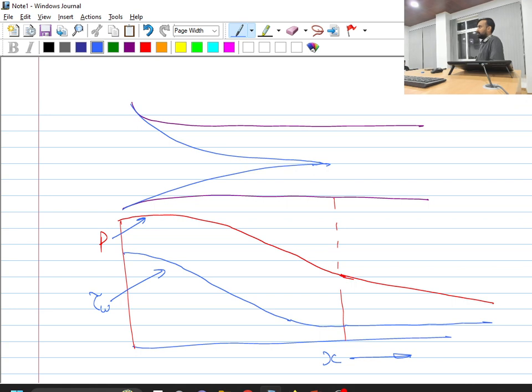Is this point clear? Say you have pumping applications where you want to transfer water or any other liquid from one location to another location. In a pumping application you have to invest a certain amount of energy to overcome the wall shear stress or the pressure drop, only then your fluid will move from one location to another. So to have efficient pumping operation, so that the pump consumes less power, our major interest is that we should have a smaller entrance region.